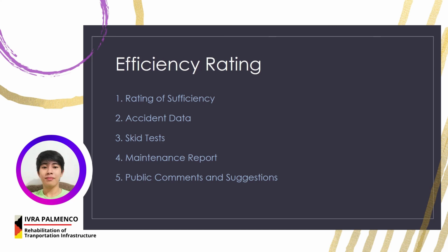Then we have skid tests. The device used in skid tests measures the frictional resistance between a rubber slider mounted on the end of a pendulum arm and the surface to be tested. This provides road engineers with a method of checking the resistance of wet and dry surfaces to slipping and skidding, both in the lab and in situ, helping to prevent unnecessary accidents that may occur due to slippage. And for number 4, maintenance report.